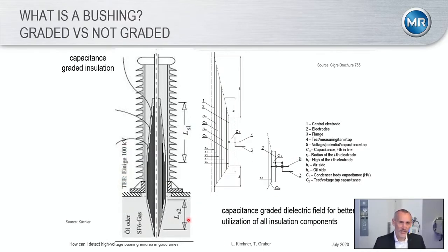What is important to say, if you grade the field here, you have the highest dielectric stress on the bushing here in the oil part, usually, where you have the foils in very narrow steps to each other, and this is the most critical part of the bushing.